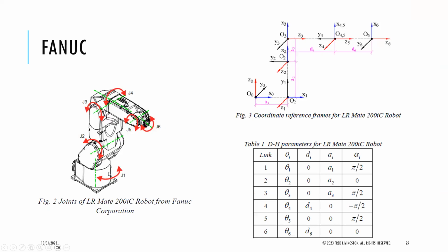Going through the same kind of thing here, this is the DH table for that particular robot. If you want to figure out why the teaching pendant is giving you these XYZs, these forward and inverse kinematics, this is what you could use, and you could do some simulation if you want to, of the actual Fanuc system. And the Fanuc also has simulators too, so you don't have to necessarily model your own. And most robot systems have simulators as well.